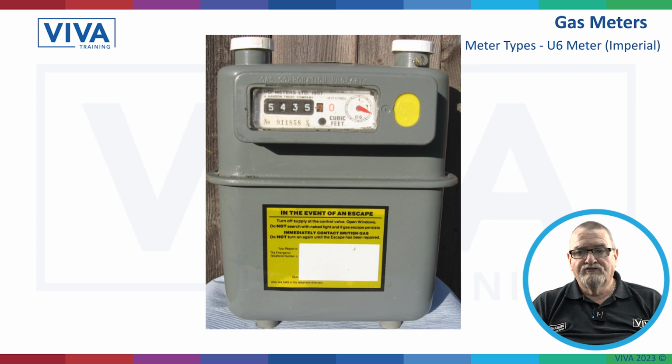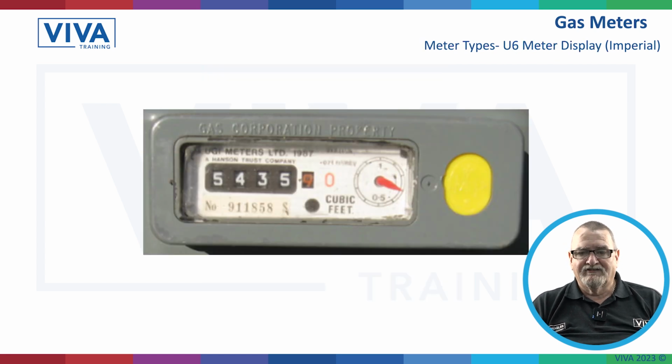That's an older U6, but it's an imperial meter. So the old feet and inches, that most of you guys probably won't be familiar with, but somebody like me, I learnt that in imperial at school. I'm of an age that learnt things like that. So that one is slightly different. Again, we've got a billing index, which are the 4 white numbers, but for testing these and checking the gas rate, we use that test dial, the one there that has the number 1 at the top and the 0.5 at the bottom, and the red hand that's going to move round.